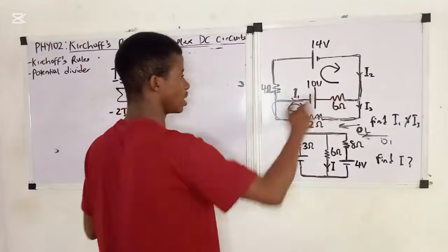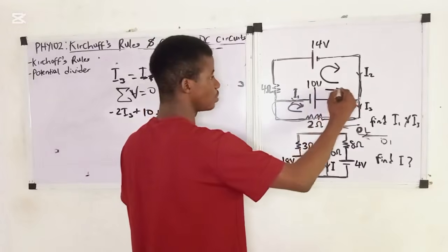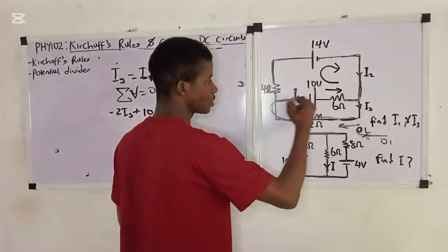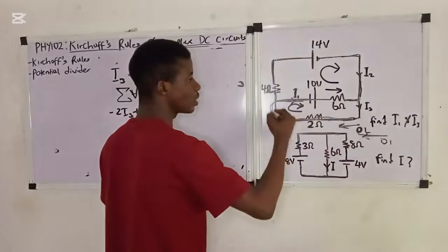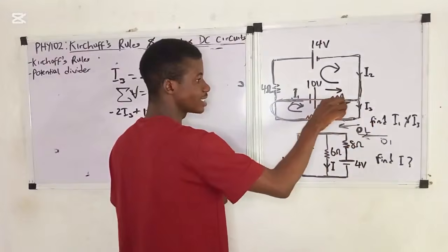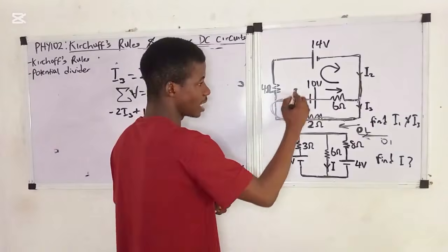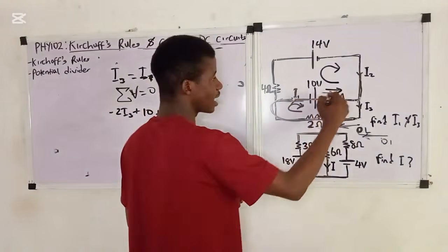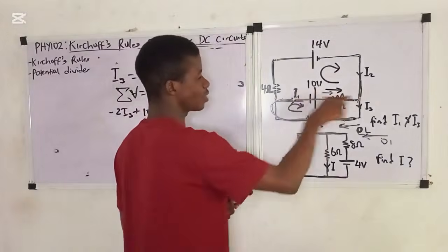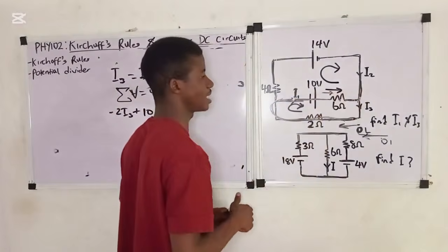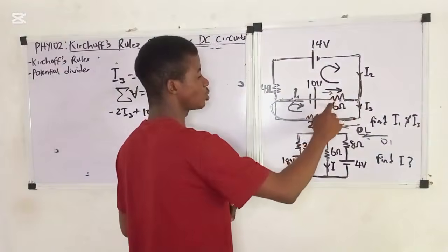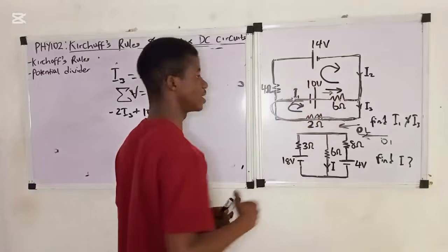We are going like this, okay? Direction of the loop is like this, right? So we are going in this direction of the loop. Then this direction, look at it. The current entering this resistor, is it actually... No, it is I1, right? I1 is going like this. So we found that both I1 and the direction of the loop are the same, right? So therefore, there will be a voltage drop in this resistor, the minus, right?